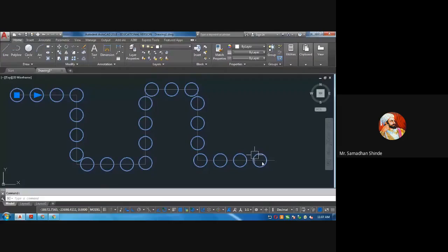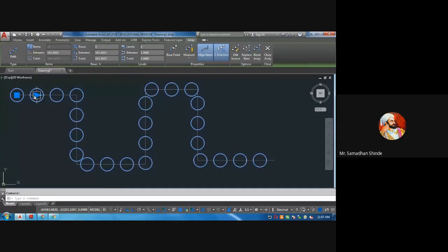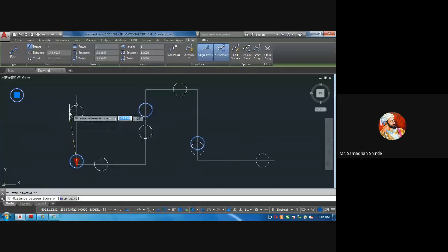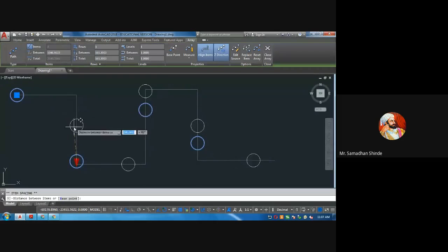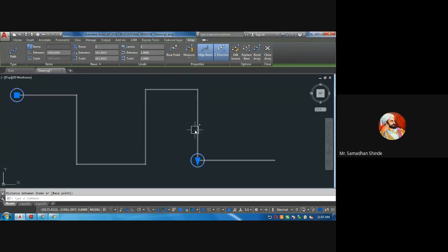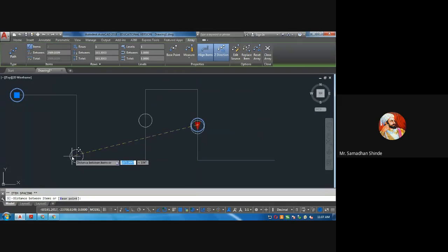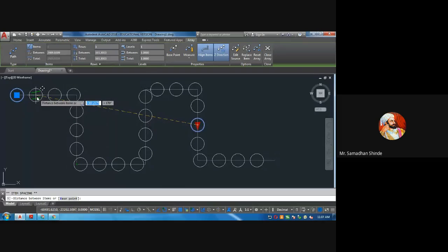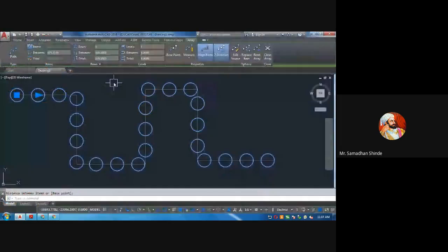You can have its grip also. So you can take its grip. Means whatever. You slowly you can take grip as well. Few circles will come. Again you can take grip to back side. You can take forward. Suppose last circle, suppose only 2 circles I will take. Again you can take, only you have to click and you have to take its grip back side. N number of circles will come like this. It is an example of path array.